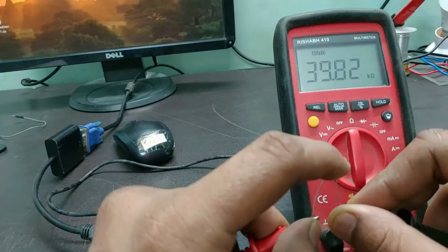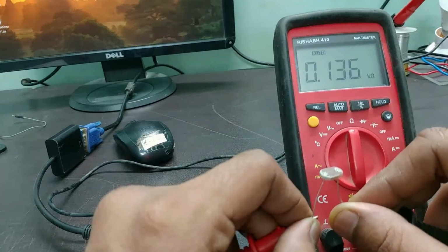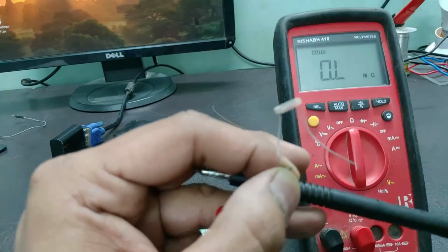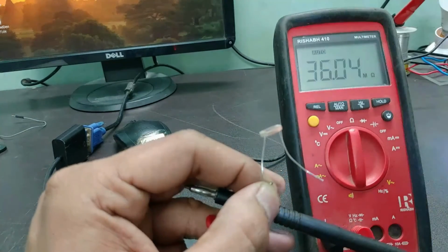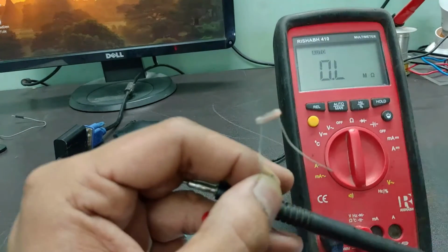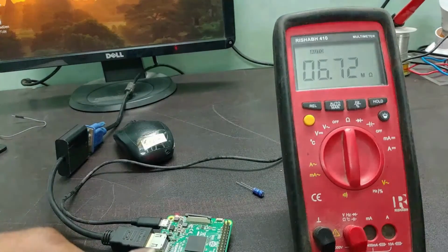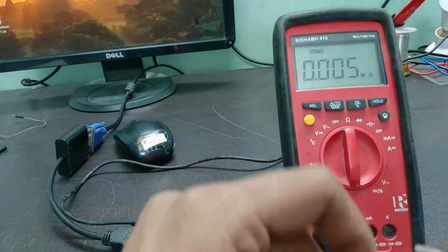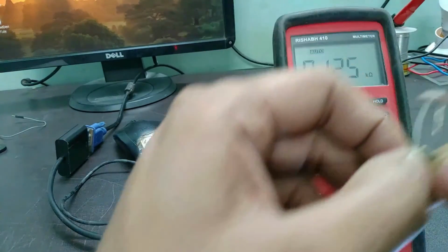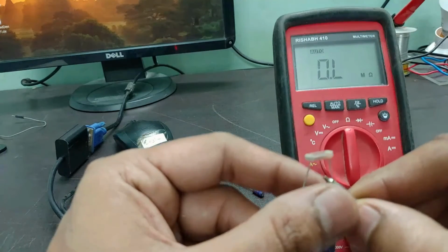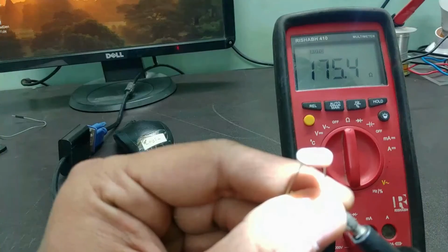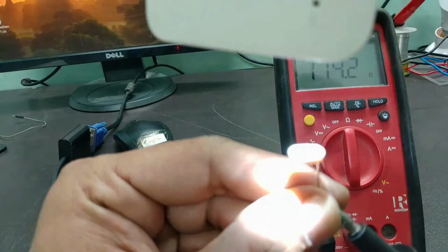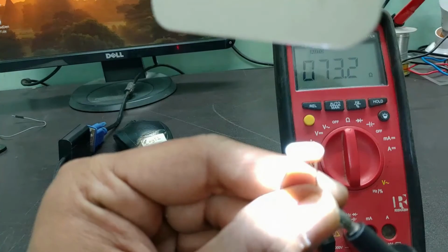That's the resistance the LDR is offering. Now if I keep it as it is, then it is 1.3 kilo ohm, and what I have here is a torch light in the battery bank. So let me just keep it like this. If I take the LDR in front of full light, I'll just hold it like this over here. Now you can see the resistance is so reduced that it's about 100 ohm and something, 70 ohm.